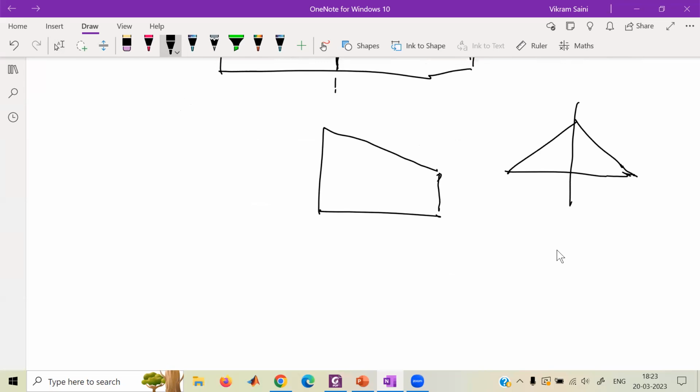It could be any shape, but the question is, at what point will the net lift act, so that we can compute the moment about the x-axis? Because by moment I mean force multiplied by distance. The distance is unknown to us. We know the change in force somehow. We'll compute that. We have already discussed in one of the classes, but I'll discuss it again, how much lift is generated when the aircraft rolls. But the critical question is, at what distance will that change of lift act. You understood the question, right?